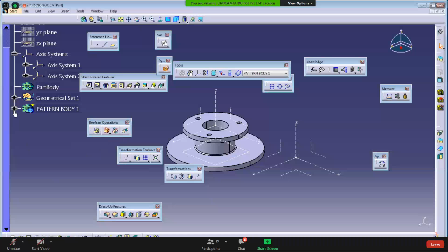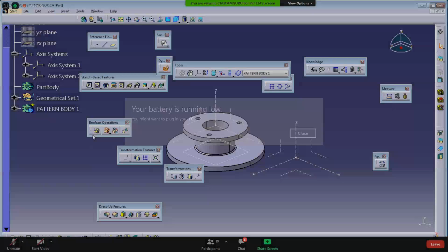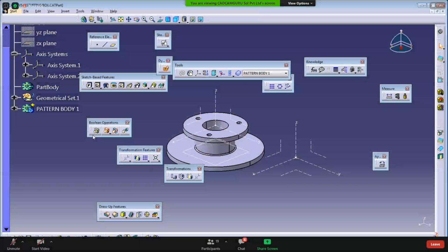With one positive body and one negative body, if I need to add them, then use this add option. Properties don't matter, both bodies become added. But if you use assemble, then it will subtract automatically, because there is a plus sign and a minus sign. Plus into minus, there will be the remove option.